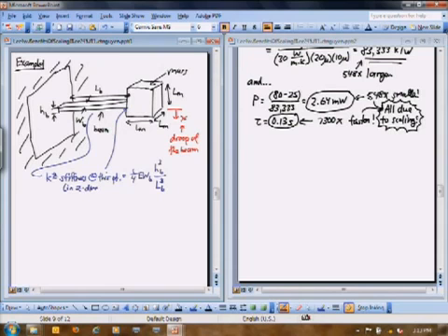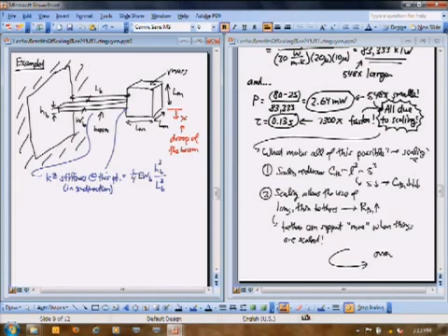Okay? All right, so what can we say about this? Why don't we look at stiffness first of all? Okay, what if we start scaling all the dimensions in this stiffness? So you know how to play the scaling game, right? That says there's a WB that scales by S. There's my HB, it scales by S cubed. There's my LB, scales by S cubed. This ends up going as S. Okay, so what does that tell us? That tells us that if I make S smaller, if I'm scaling everything, then my stiffness is going to get smaller. Okay? And that's not good, right? I mean, basically I was trying to claim that when you make things smaller, you droop less. Right? But in this case, we're seeing the stiffness get smaller.